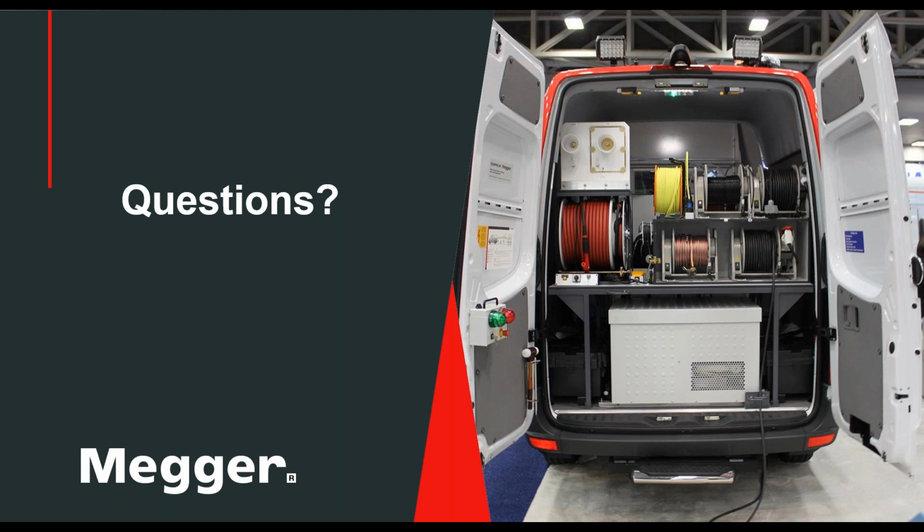But if you had a multi-branch system like in the cities, then you typically use a different method, and that's what we call current chasing. Okay, you're thumping and you're using a galvanometer, and you follow the fault current. You open up the manholes at the branch points, and you see which way the current will go when you're thumping, and that will eventually lead you to the fault. That is the typical method in branch downtown city networks.